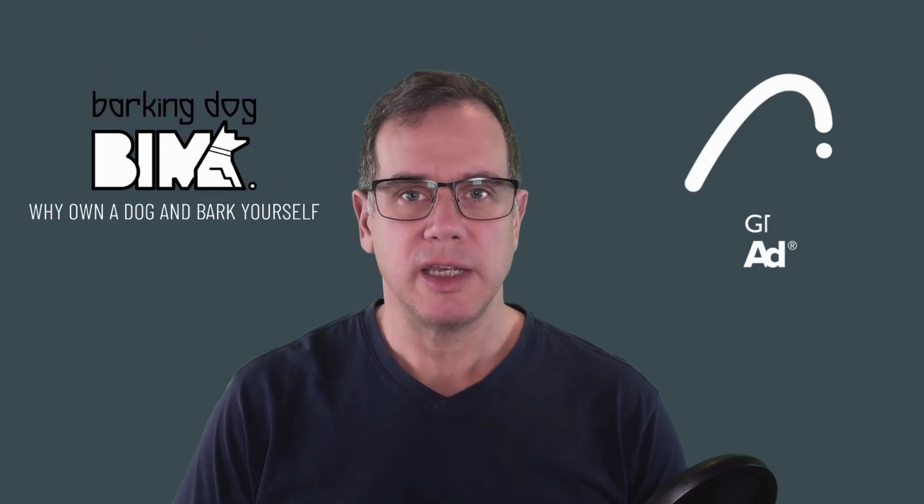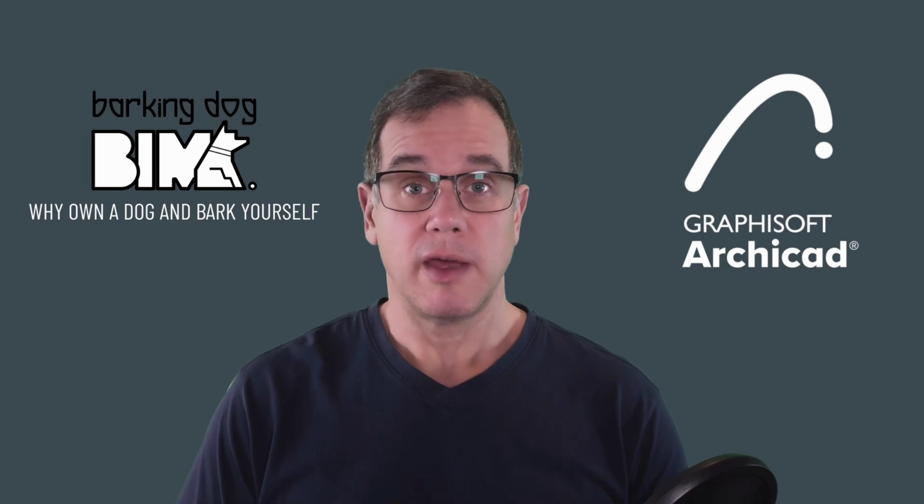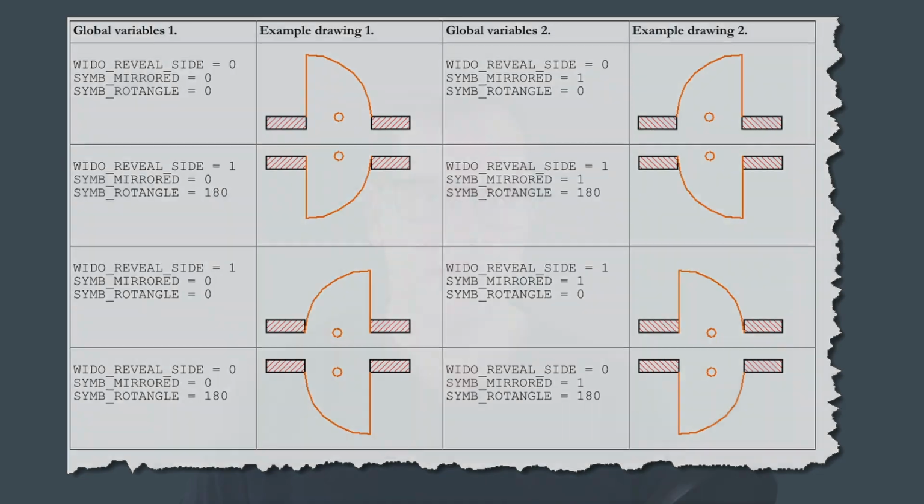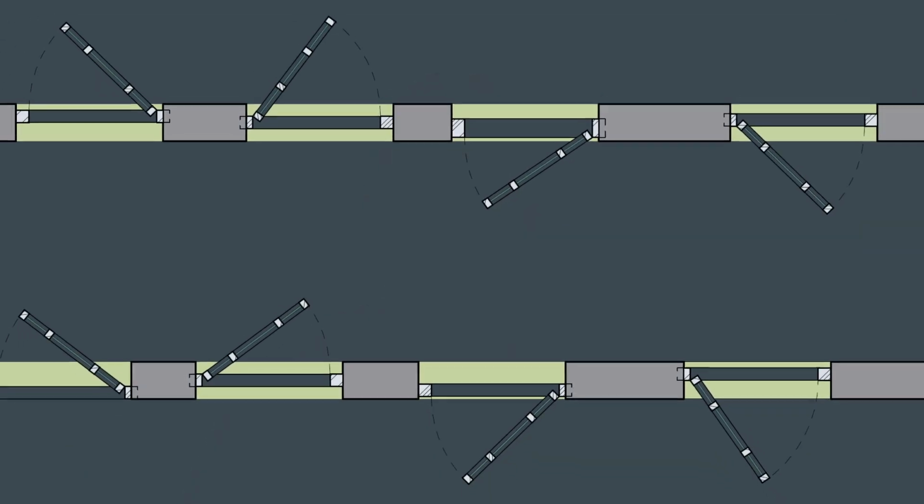If you're just joining us, we are up to part 15 on a series of creating a fully custom door in Archicad using GDL. We've covered quite a bit so far, and what we're going to look at today is what's involved in creating the hole in your wall for your plan view. Believe it or not, this is done using the Wallhole 2 command. When placing a door, you need to account for the 8 different placement methods, the wall thickness, and the reveal depth. I'll show you how to do that.